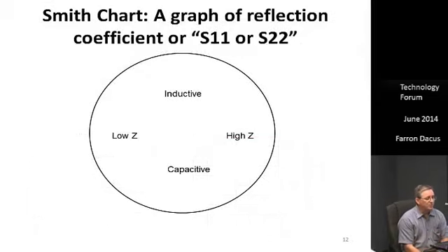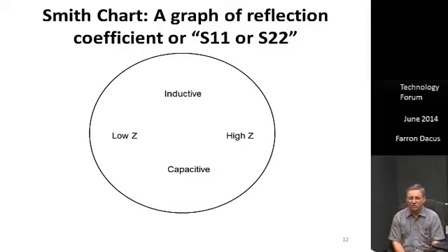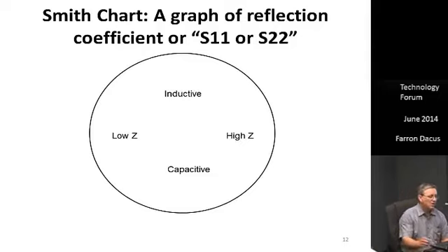Okay, the Smith chart. Not a lot of time to get into tremendous detail on this, but this is a very common circuit design tool that basically represents reflection coefficient, which naturally has a magnitude and a phase angle. To keep in mind on the Smith chart, it's normally got these odd looking lines and circles. It's filled up with those when you see one, and it kind of hides the fact that there are some regions here that are very helpful to keep in mind.